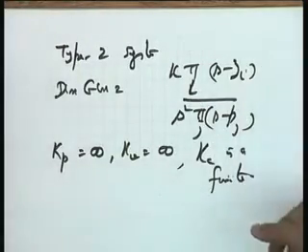I am making a statement that in general, most of the control systems we come across, general applications where there is no specific demand from the user, in that particular case a 0 steady state error to step and a finite steady state error to ramp is more or less okay. So, as a general guideline, if you have to make a quick decision as to what type of controller you want, you look at the plant.